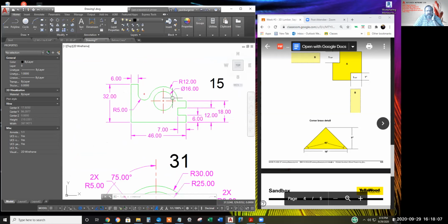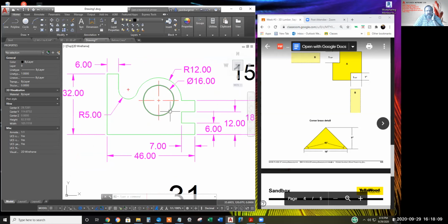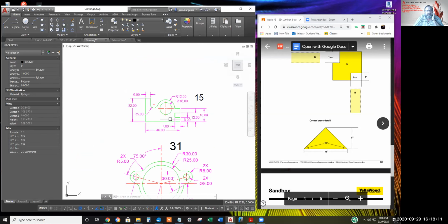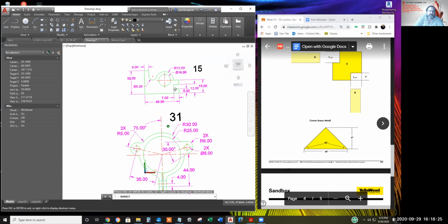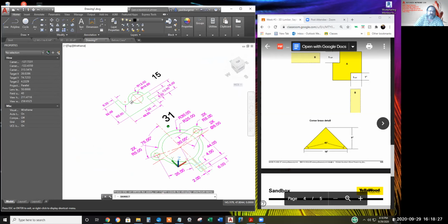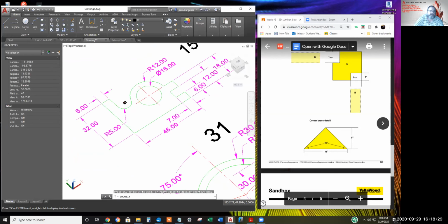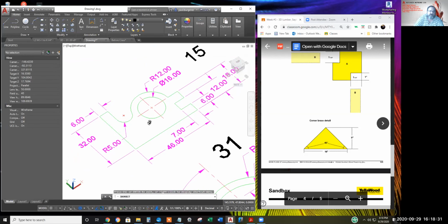And there's a hole in 15 here. A couple other students didn't successfully P-edit join all the arcs and lines for the perimeter together, and ended up extruding it into simple surfaces. Let me show you what happens when you extrude it into simple surfaces.